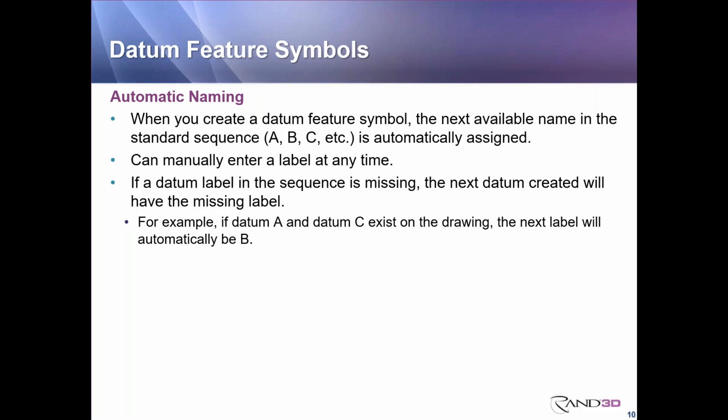Now, to display a datum feature symbol in more than one drawing view, you must manually name the subsequent datum feature symbols to the same name as the original one. So that's a side note there.